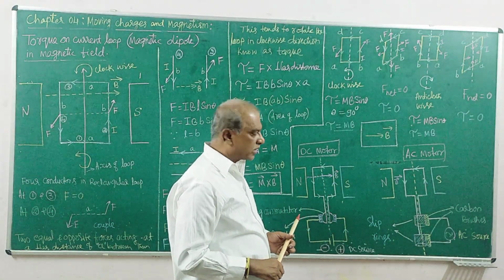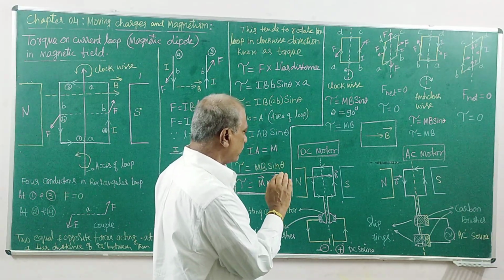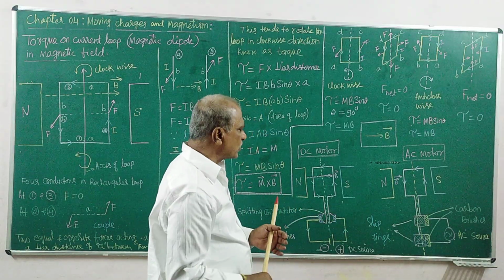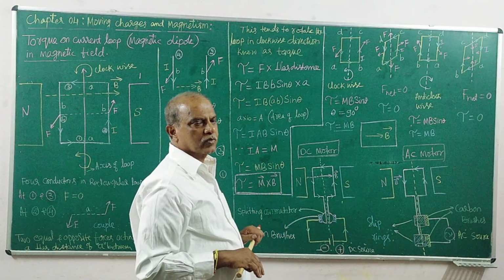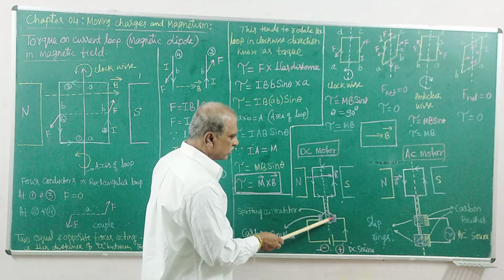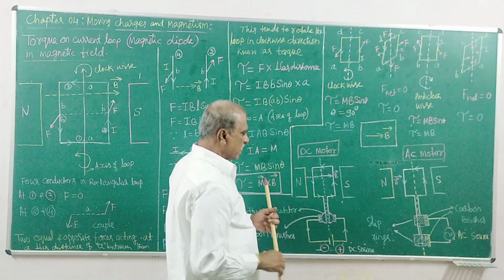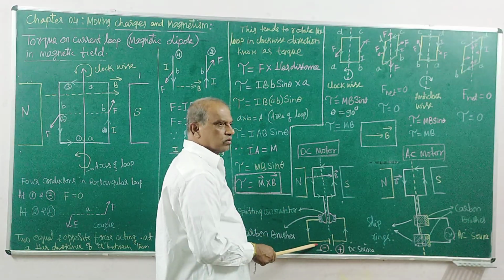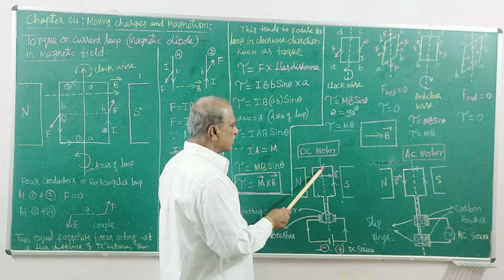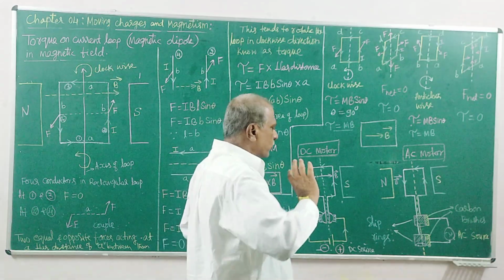But the direction of current you are giving in the circuit remains the same, and it looks like the previous one. This is because the commutator reverses the polarity for every 180 degrees. Plus becomes minus, minus becomes plus. That is why the current direction in the loop looks the same while you are giving rotation.